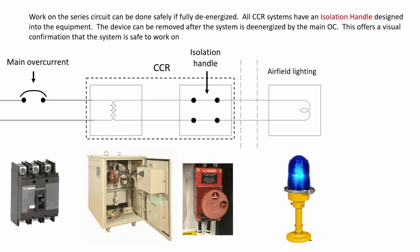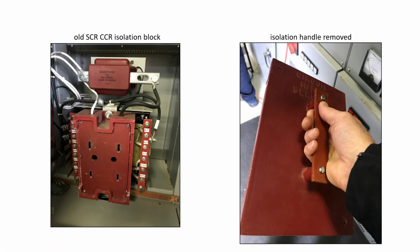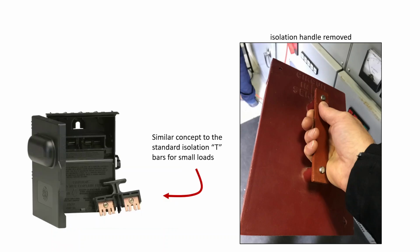Now, work on the series circuit can be done safely if fully de-energized. All CCR systems have an isolation handle designed into the equipment. The device can be removed after the system is de-energized by the main overcurrent device. Remember, that supplies the CCR. This offers a visual confirmation that a system is safe to work on. So that's this here. Older systems will have a much larger block that looks like this. And realistically, it's very similar in concept to a standard isolation T-bar for smaller loads, like you would see for, I don't know, a heat pump on the outside of a house.